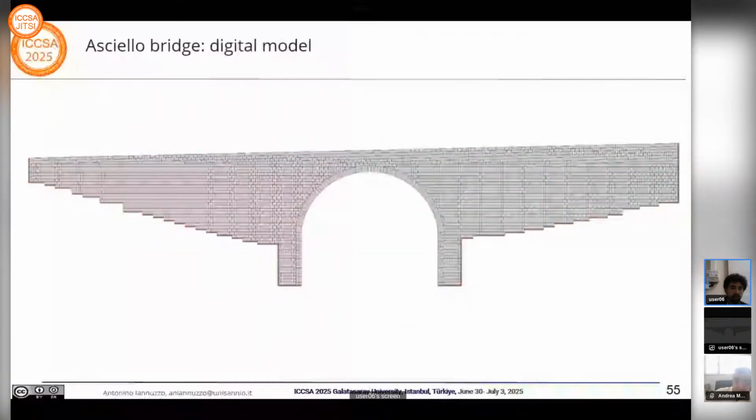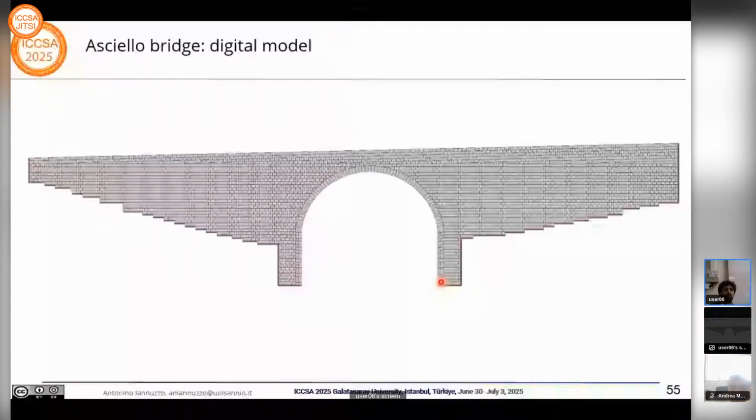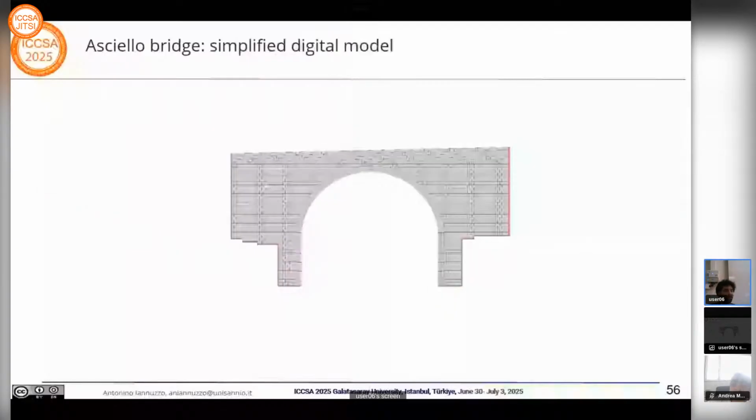The first analysis we did was a displacement capacity analysis of the right pillar. The first run, with a random displacement just to understand the computation time, with also the reduced value of the stiffness and so on, took more than 1 day. So we decided to analyze a smaller part of the structure, like this, with this kind of boundary condition. You can see the red blocks are supports, and on the right we apply a displacement condition. This is essentially the layer we consider in the analysis.